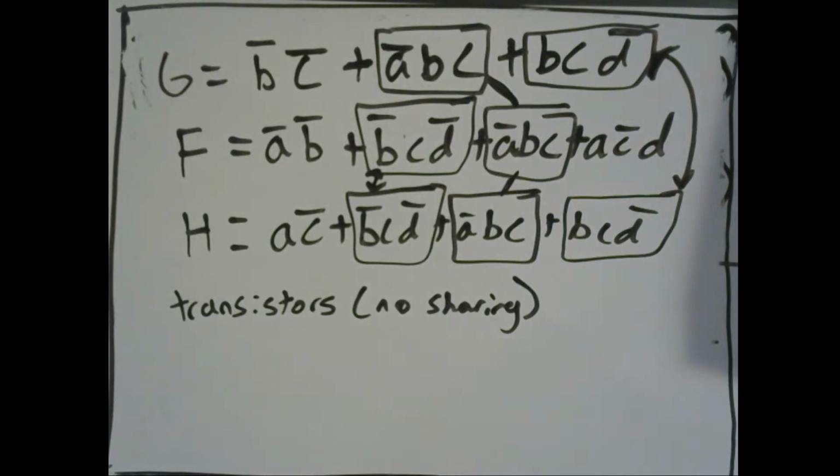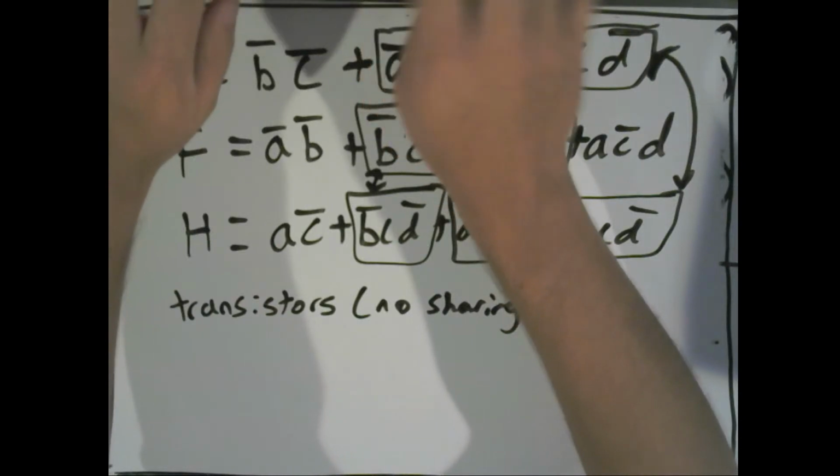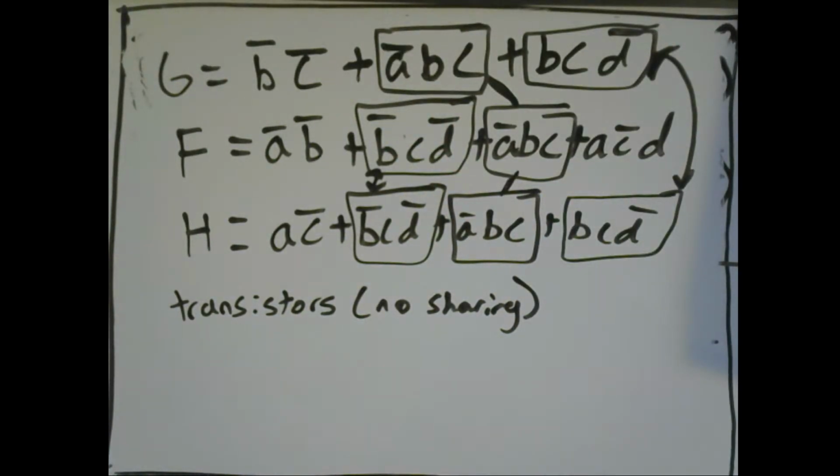I'm not sure what she is saying nowadays, but I'm not sure if anyone has insights about that. But typically, how to calculate transistors is you want to count 2 times the number of inputs plus 2. Okay, so that's the formula we use. So we would count all the inverters.